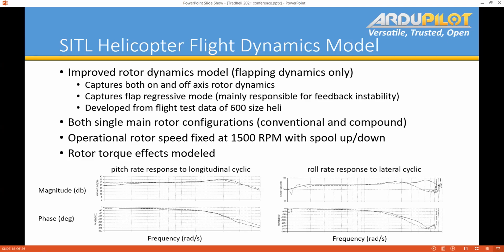When you ID it, you have to set a structure for your model. You say, well, it's going to have speed stability derivatives, damping derivatives, and control sensitivity derivatives, and you set the model based on what you know is going to be in the aircraft. Then you go through the process of what CIFER allows you to identify, based on the frequency sweeps, what the derivatives should be.